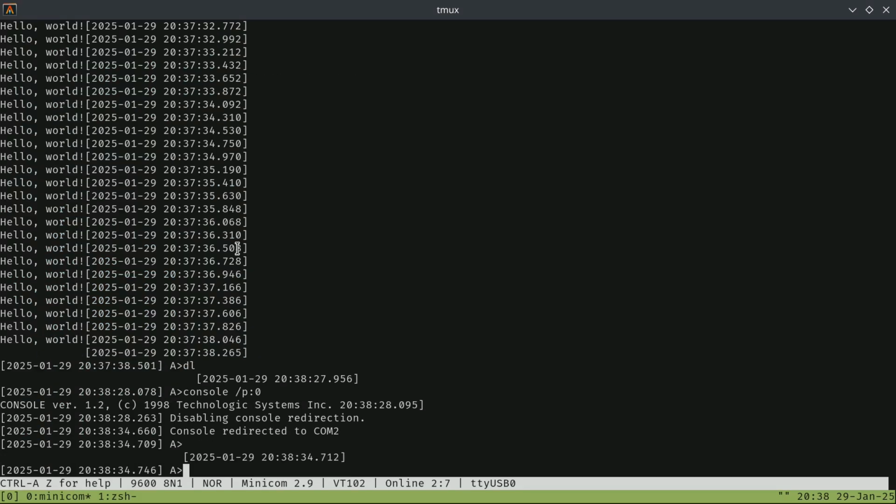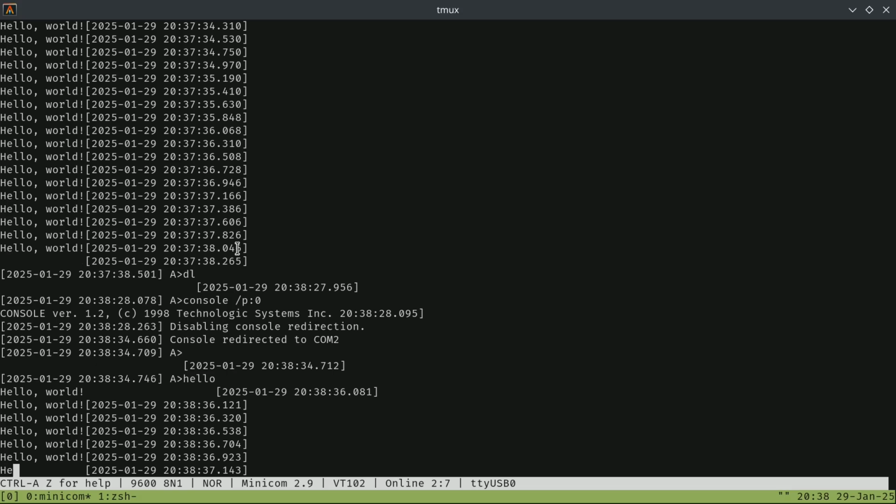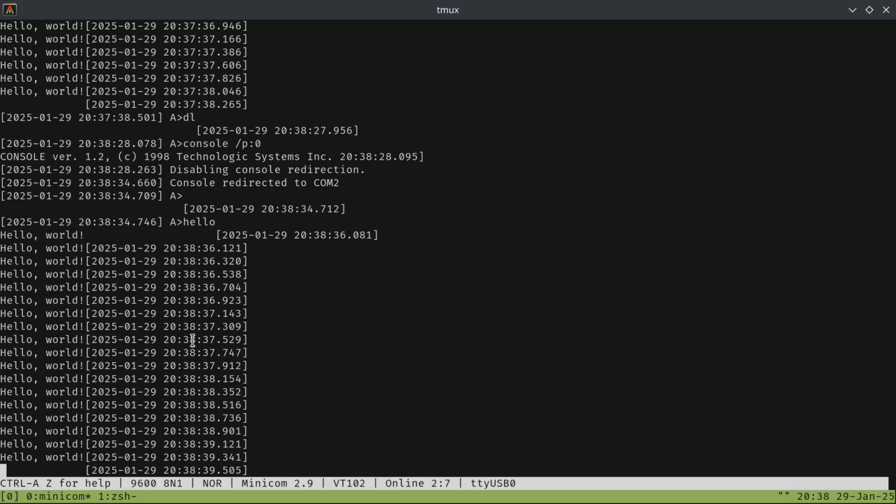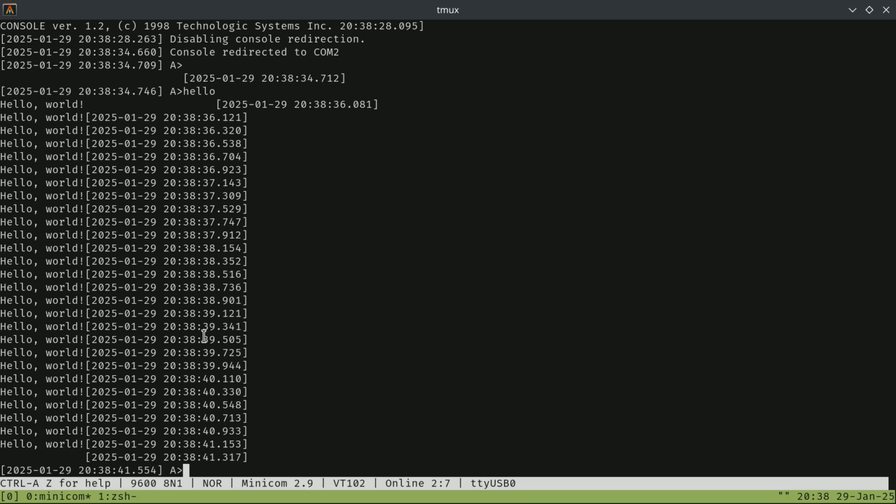Now when we run the program, we can see that it waits an average of 200 milliseconds between printing our message. Sometimes it waits a little bit less, and sometimes it waits a little bit longer. If we wanted more accuracy out of the system, we'd need to take over one of the system's programmable timers, but that's quite a bit more complicated of a solution. This is perfectly fine for now.